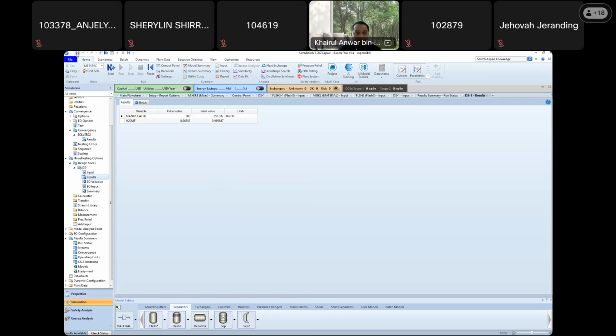All right. So to get 97, you need a lot more MIBK, another 300 to 400 extra kg per hour, just to get the 2% increase. It depends on your process. If you really need that 97% quality, then yes, you need that 556 kg per hour.